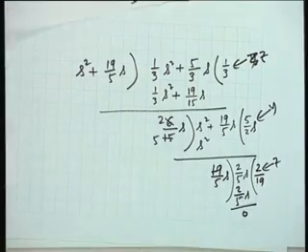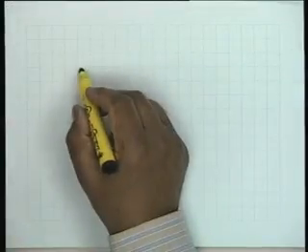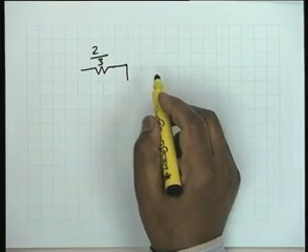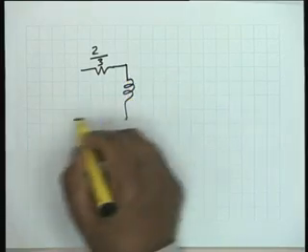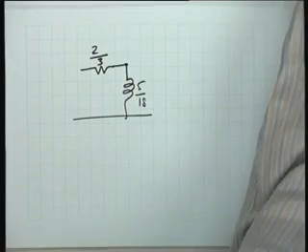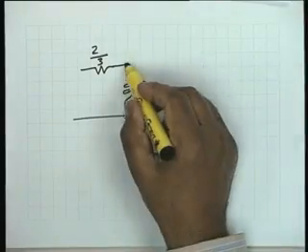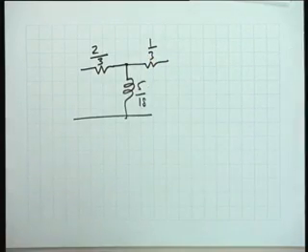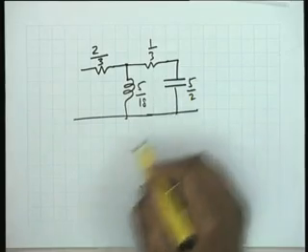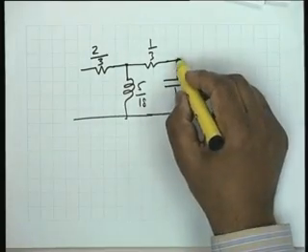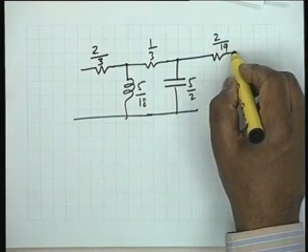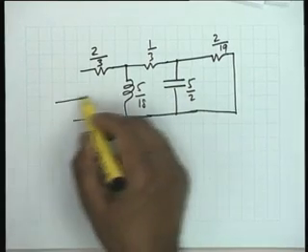So, my circuit would be this. 2/3, then what would this be? Inductor 5/18. The next one, before that there is a resistance of 1/3. Next one is a capacitor 5/2. That was the effect of reversing the order. The next one is a resistance 2/19, and then the remainder is 0. Impedance 0 means a short circuit. So this is the total circuit.